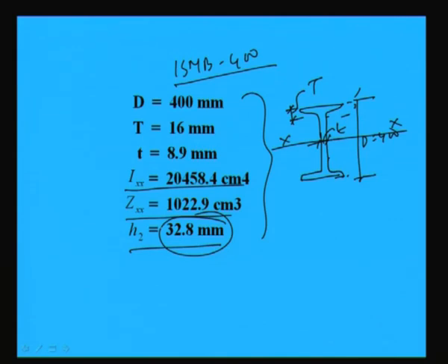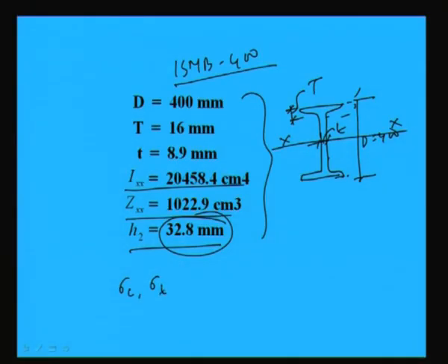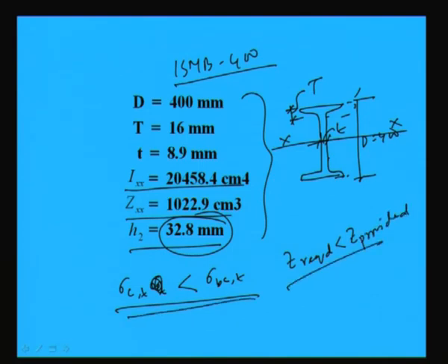So, we are seeing that as we are providing a section modulus a little higher than the required, from the bending moment point of view, this will be okay. That means the sigma bc or sigma bt will be less than the allowable sigma bc or bt, right. So, that we can assure, because Z required is less than Z provided, which is more. So, definitely this will hold. Next, what will we do?